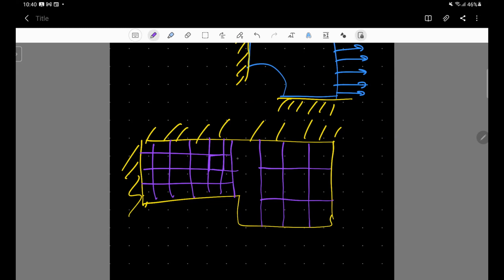In such cases, in order to make a continuous transition between these two different mesh sizes, since this would be a drastic change when we move from the smaller mesh size on the left hand side to the larger mesh size, this has to be supported with continuous triangles, so that your mesh would be continuous and compatible, without large discontinuities which might be prone to errors, unrealistic deformations or displacements, and unrealistic stress levels within this particular region.